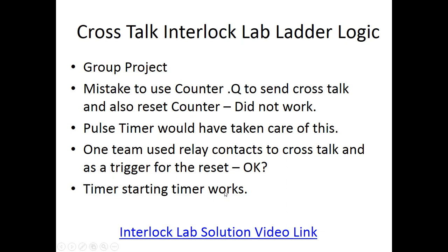I'm putting them in series. It's better to use bits and kind of break them out, and be sure to use an M bit associated with that done or that Q bit. Take a look at this Interlock lab solution video. I'll show you some ideas there.